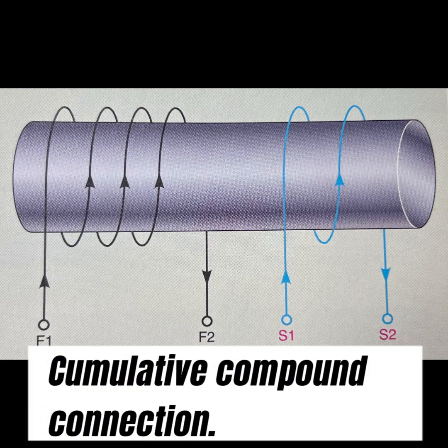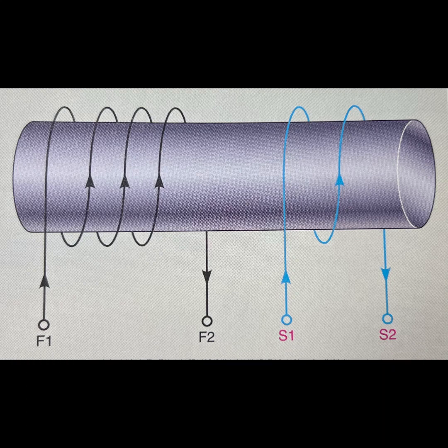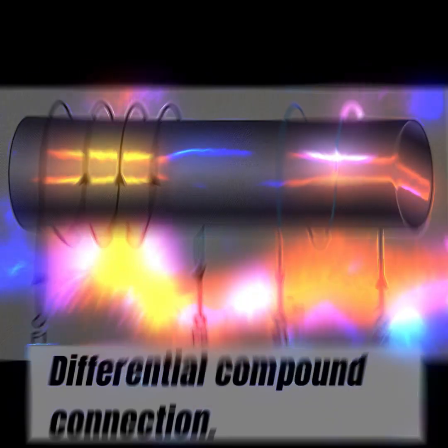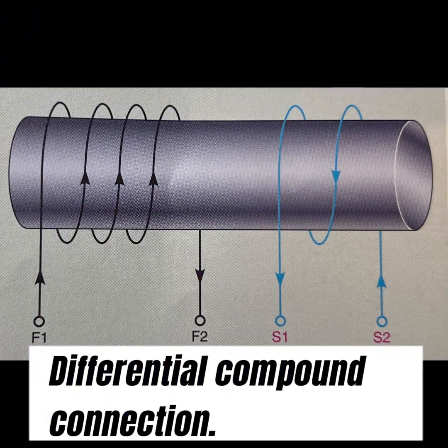Carbon brushes, which press against the commutator segments, supply power to the armature from the DC power line. The commutator is a mechanical switch which forces current to flow through the armature windings in the same direction. This enables the polarity of the magnetic field produced in the armature to remain constant as it turns.